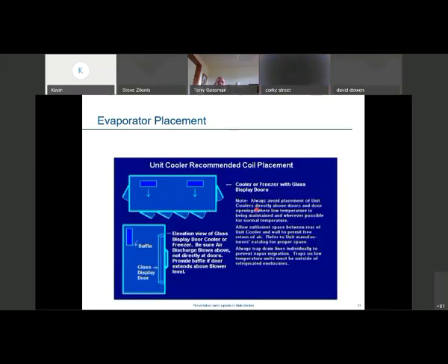So when you have glass display doors, you want to blow at the glass display doors just to keep the moisture off the inside, the condensation, that kind of thing. But you don't want to blow out through the door. So it's shown here to use a baffle to blow that air. That air coming out of there will blow above the door and drop down through there, washing the surface of the door and taking that moisture off of it.